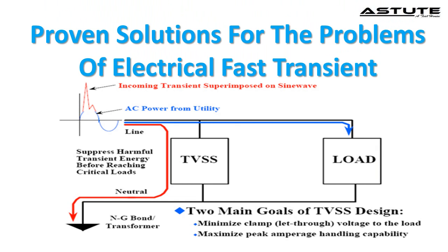There are different ways available to remove the electrical fast transient voltage entering the device, given below. Filter the incoming EFT current by installing a ferrite core around the cable carrying the incoming current. Use shielded cables. Shielded cables can limit the EFT current that enters your UUT because EFT-induced shield currents can be diverted to the chassis. A shielded cable works best when you can roll its shield braid back over the insulator before attaching the cable to a connector.